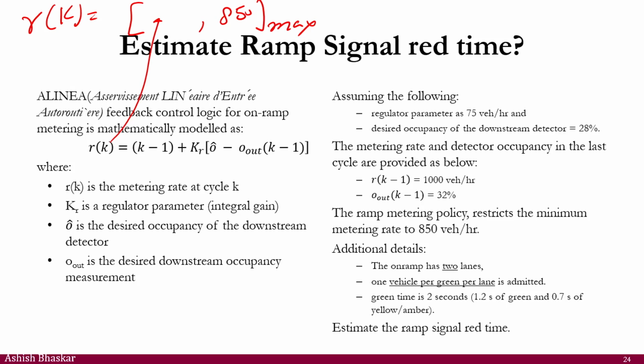It cannot be less than 850. You'll be using it at 850. And from 850 you apply the same concept: get the headway and make it twice, because don't forget there are 2 lanes. Or just convert 850 by 2 and get the headway.